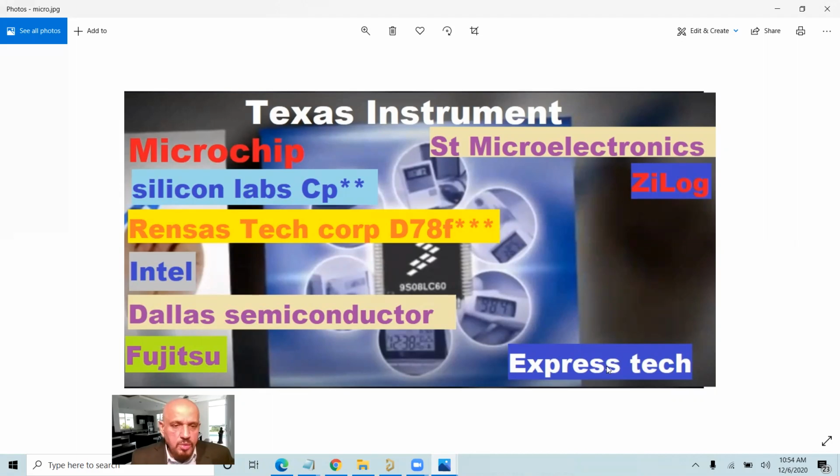They sometimes do that. You make one board, and just because you don't need to change the codes all the time, one product is designed, you don't need to upgrade it. And if you need to upgrade, you just need to upgrade your software version. Their hardware pins are going to remain the same because the body and function are already designed. So what they do is go for OTPs, one time programmable. They burn them once, and then they are finished and cannot be reprogrammed, and they are very cheap. Why? Because then they have no more non-volatile memory inside. If there is no non-volatile memory inside, the structure is going to be very easy.